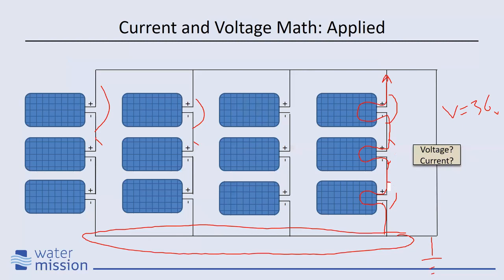Well, if I forget everything else other than these 3 panels, I know that these panels in here together are in series, right? So I know that that is just going to be 3 amps coming through there. Now also, if I forget and just look only at this second string, these panels are in series with each other, okay? And so that's going to generate 3 amps also.